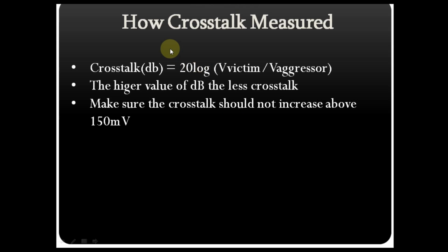The last topic is how crosstalk can be measured. Crosstalk in dB is given by 20 log of voltage of the victim divided by voltage of the aggressor. The higher the value of dB, the lesser the crosstalk. Make sure that crosstalk does not increase above 150 millivolts.